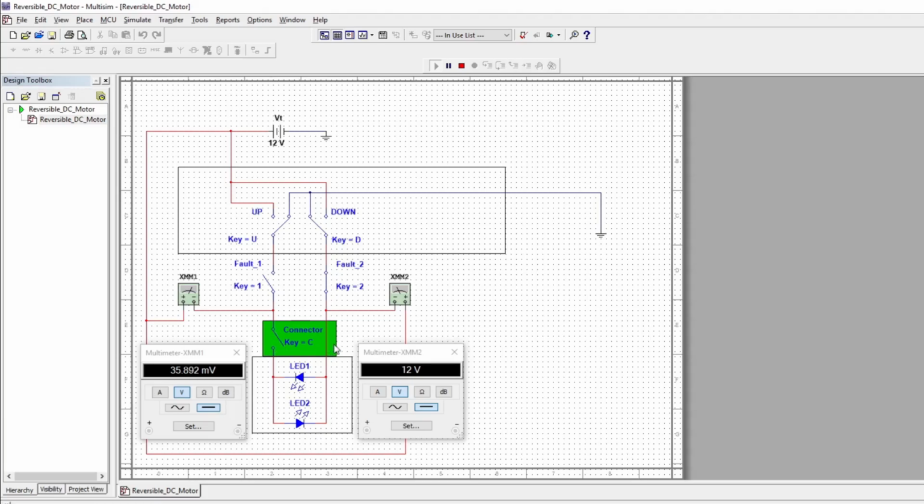Now you may say, hey, you didn't disconnect this. If you pulled this connector, both wires would come off. Yes, they would. But all you need to do is prevent backfeeding, so it really only requires you undoing one. Now, in the real world, this connector is one connector and 2 wires go through it, so you'd be disconnecting them both at the same time. But for this demonstration, I'm just doing one to not clutter things. It's the same thing electrically. So you can see the key point here is disconnect the load.